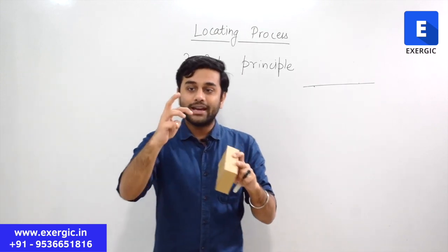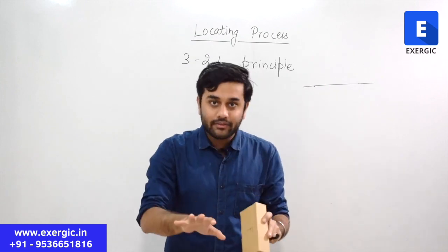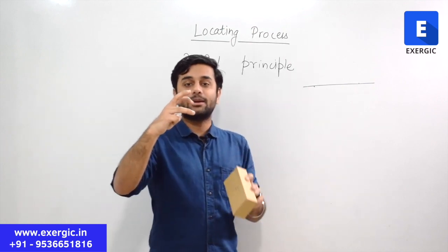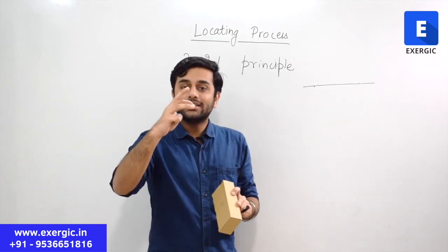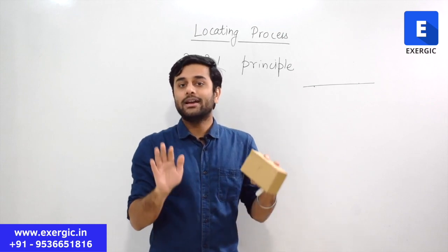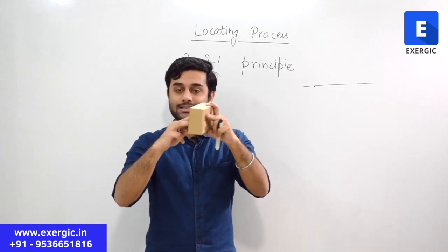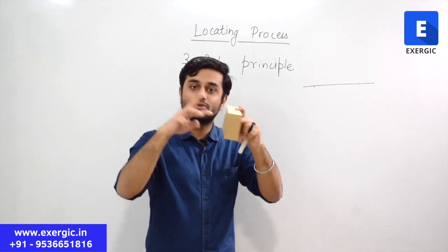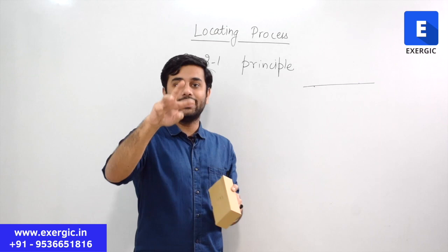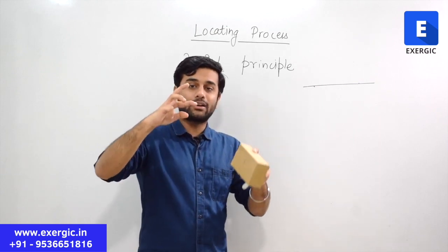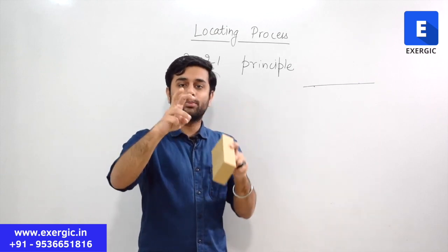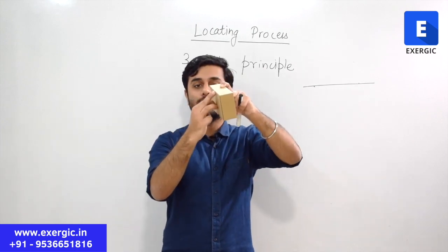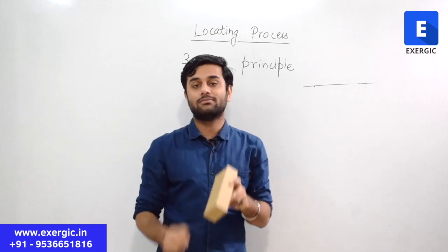Because when you are defining 3 points, in a way you are defining the plane as well. Whether these 3 points are in the vertical plane or slightly misaligned, it does not matter, because you can adjust the workpiece such that it contacts those 3 supports. Those 3 points, I have told you, no matter what their orientation, however you hold 3 points in your hand, you can always pass a plane through them, no matter what alignment.